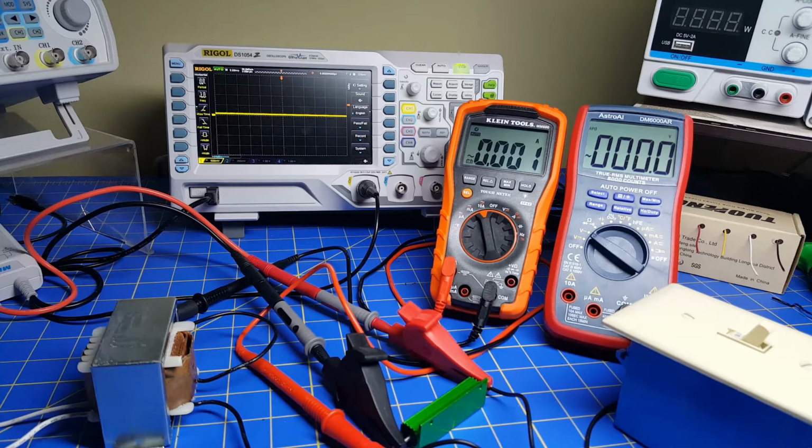Okay, so I've got my variable transformer. I've got it set to 0. I'm going to turn it on. It's on now. And I'm going to turn on the on switch to apply voltage to the transformer. And you can see I've got 0 volts. And I'm going to increase this. Now we've got 30 volts. We're starting to get a waveform on the current. So I'm going to bring it up to 120 volts, which is normal voltage.